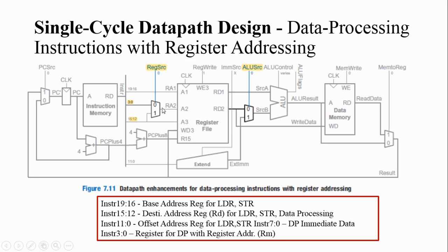So for the second operand register, in order to read, you are using one more multiplexer here, right? In order to incorporate all the operations, if the register source control bit is 0, you can select the second operand and give it here. If register source is 1, you will be selecting this one as the input, because in the load operation you need to connect this as the destination register. Right, and the store operation should be like that.